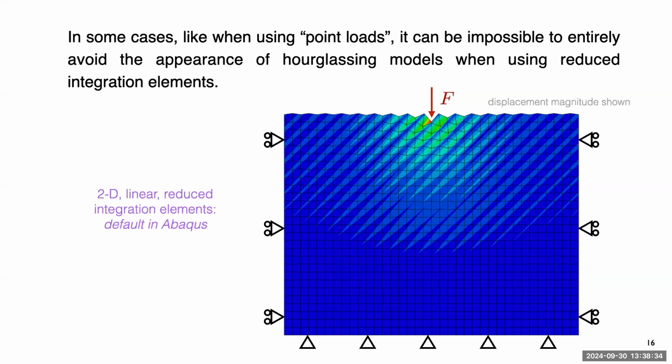If you ever see your elements going like that, and you're not sure if it's physical or not, it's probably artificial. If the motion of your elements is exactly the frequency of the elements, it's more likely than not an artificial thing. If you're not sure, change the mesh. And if it's still the frequency of the mesh exactly, then it's probably the mesh. It's not the underlying material.